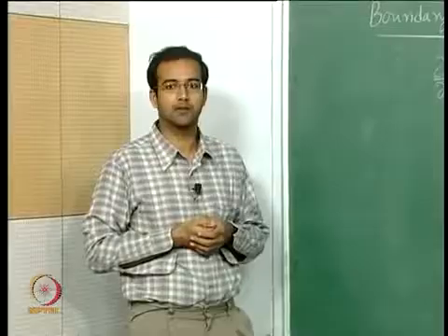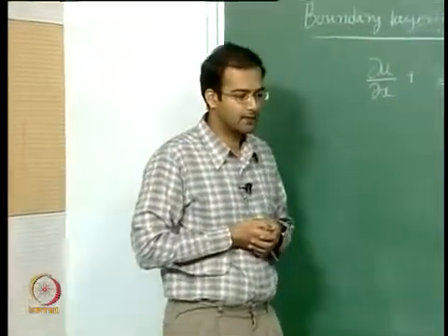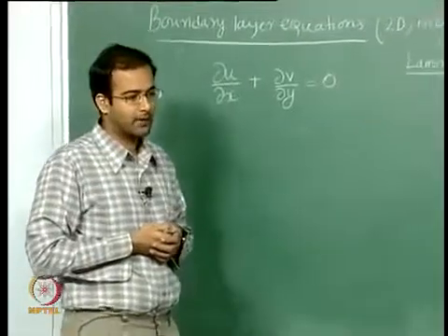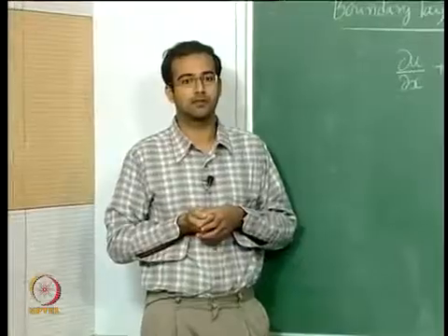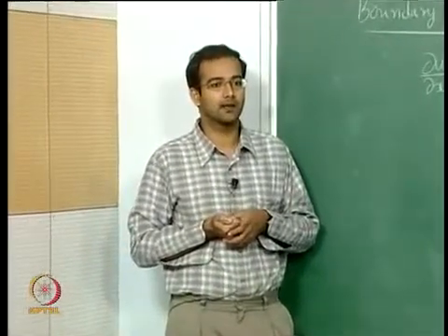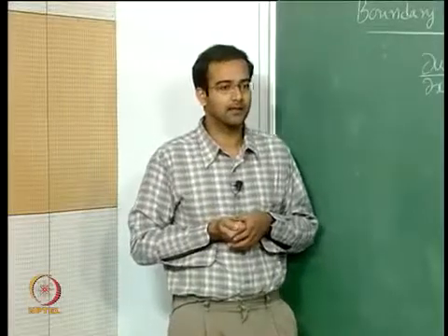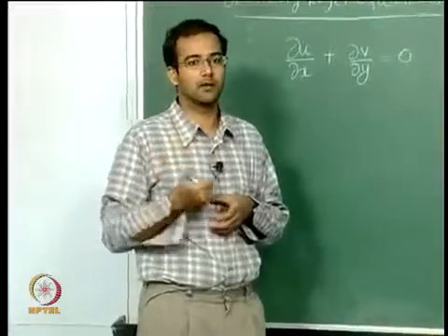For unsteady problems we can do time averaging, and when we do this averaging we are trying to get information only on the mean properties of the flow, such as mean velocities, mean pressures and mean density. We are not interested in all the microscopic turbulent fluctuations and turbulent quantities.